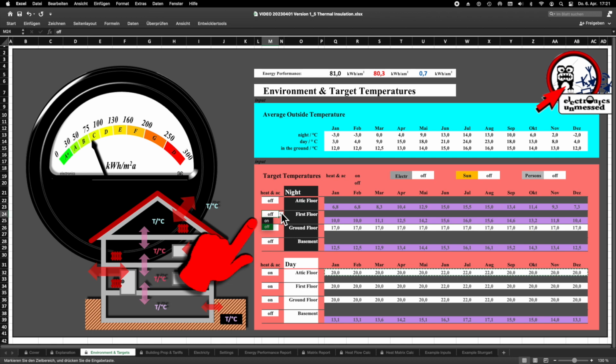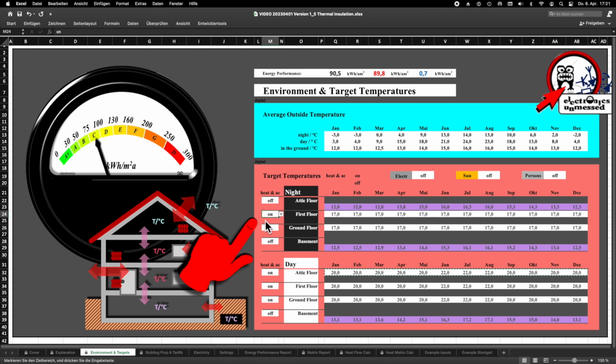Incidentally, we could also use this to calculate the outside temperature at which frost would occur in the attic in this scenario. We are now at an energy consumption of 90.5 kilowatt hours per square meter per year. The saving of heating energy would be about 25%, and we achieve that without any investment in renovation measures. Of course, this does not replace modern thermal insulation, but you can obviously save a lot of energy by your own behavior. Here we simply quantified it.